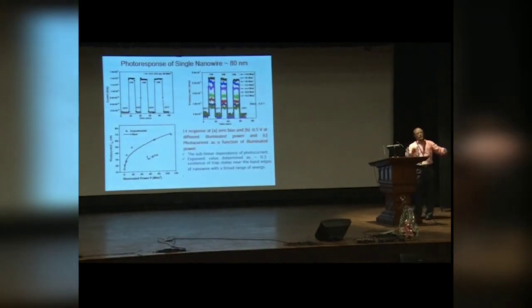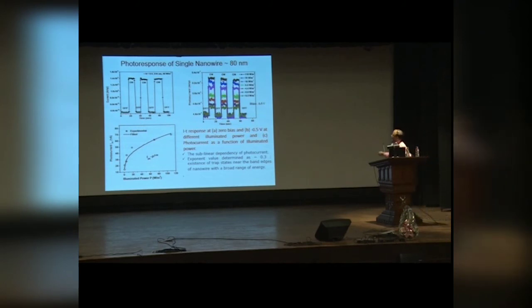Again, this is not a junction, this is a kind of photoconductor, metal semiconductor metal. So you don't get so-called junction characteristics in the IV, but you get good optical switching characteristics, either using lasers or light source of different wavelength. So even at 0 volt, you get a nice optical switching. And this is a kind of power-dependent optical switching. This we have shown by the argon laser, 540 nanometer. As you increase the power, of course, it should increase. That's what is happening. But of course, if you take the photocurrent as a function of power, it goes sublinearly.